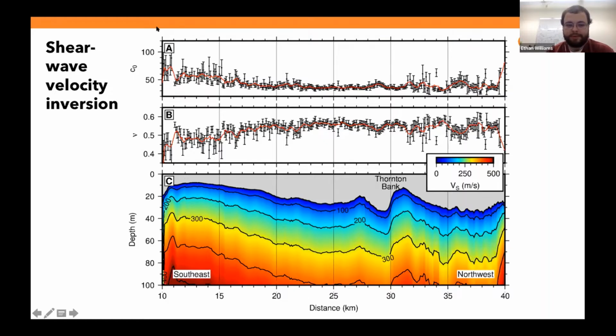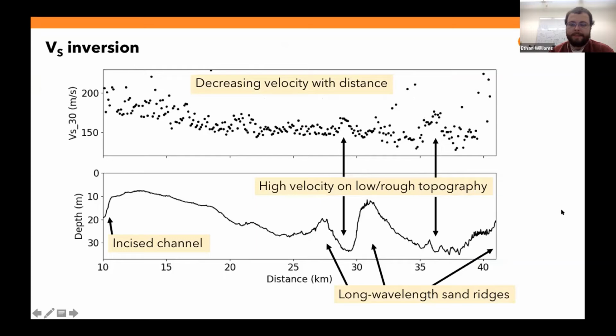The cable traverses a couple interesting features. On the far left, it goes across a shipping channel, which was cut for the port of Rotterdam. And then as it comes off the continental slope into slightly deeper water, still very shallow though, there's several really large tidal sandbanks with many small dunes on top of them. And in between those, it's incised down into a lower Eocene clay layer. So we have some contrast between sand and clay. And we can see these in our very simple model data set.